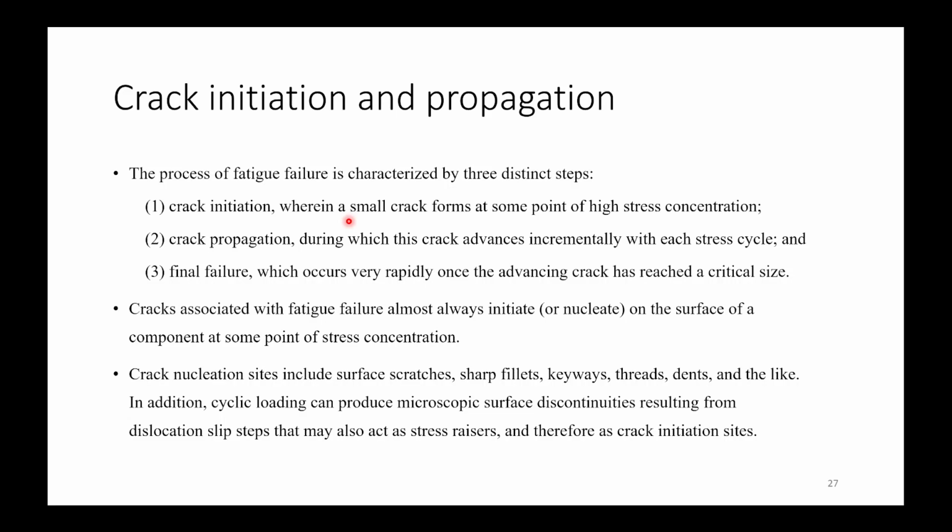These points can be because of presence of some inclusions, some stress raisers, or they can initiate because of formation of extrusions and intrusions that will be studied further. Second is crack propagation, during which this crack advances incrementally with each stress cycle. And final failure occurs very rapidly once the advancing crack has reached a critical size.